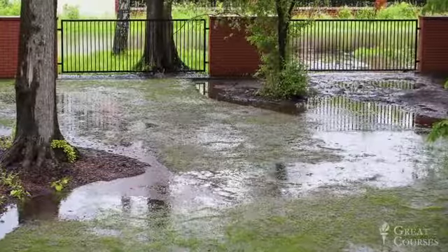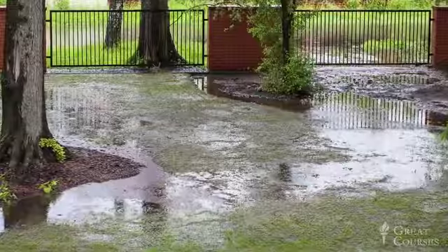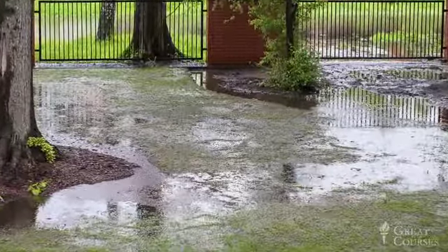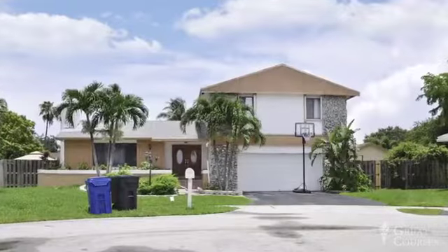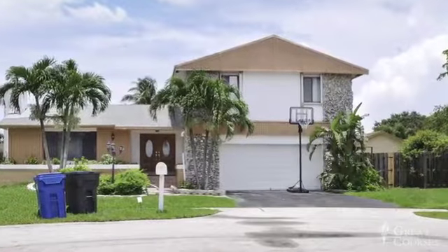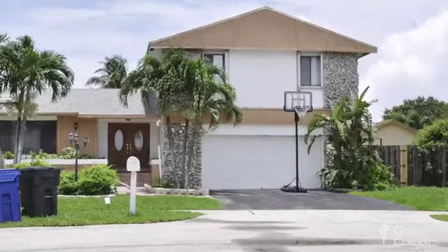Storm drainage design is primarily concerned with surface water, and while this stuff constitutes a tiny portion of the Earth's water supply, it can cause big problems for homeowners and developers. As we've already seen, if precipitation that falls on your lot isn't directed away from your house, some of it will seep into the soil around your foundation and may find its way into your basement. And if your lot adjoins higher ground, storm runoff will generally flow from that ground onto yours, exacerbating the challenge of conveying surface water away from your foundation.